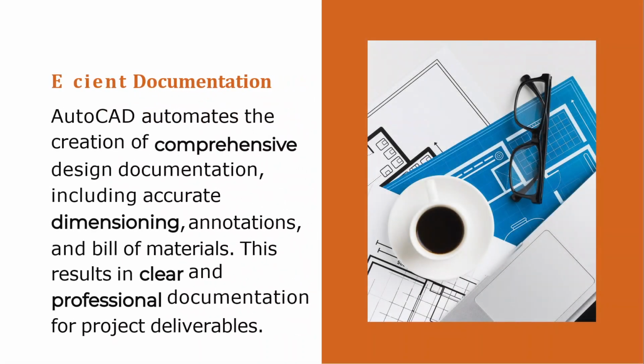Next, efficient documentation. As I was telling you, execution is all about following drawings. If you are following the design process, what they designed in AutoCAD, then your execution will be perfect. That's why documentation is important. And when you don't have that documentation feature, assume that you are giving a drawing to the execution team. There will be a few revision drawings also. If you don't save your previous design revisions, and the execution team loses the printouts, the hard copy they have, then it will be a big problem to go back and redesign the same again.